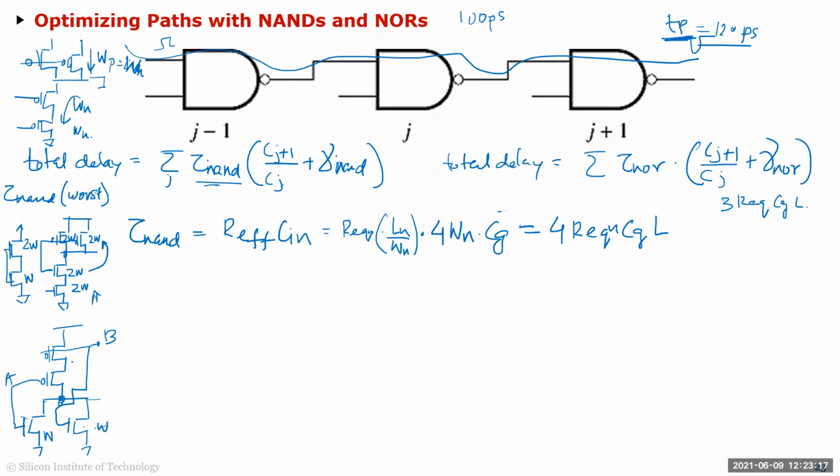And for the PMOS to have the same size, then this needs to be 4W, 4W, because then the series is 2WP. Because PMOS is twice as slow, but you have two in series, so you have to put twice as big to get the series resistance same, and then twice more to get the mobility and the V saturation point low. So because it's the PMOS in series, now you get 4 times more. So NOR gate is now worse than the NAND gate because of that.